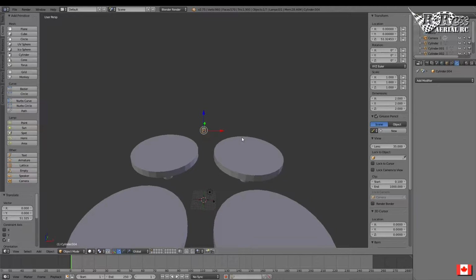So those were 55. If I go to 56, that's half a millimeter on each side. If I go to 57, that's a full millimeter on each side. When you're doing ducts, you want to be very close with your propeller edges. If not, you lose the actual efficiency that the ducts are supposed to give you. So I'm going to do 1 millimeter clearance all the way around, which is 2 millimeters over the whole diameter. So I'm going to do this as 57 by 57.